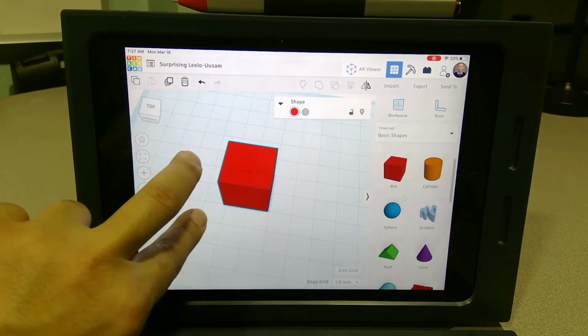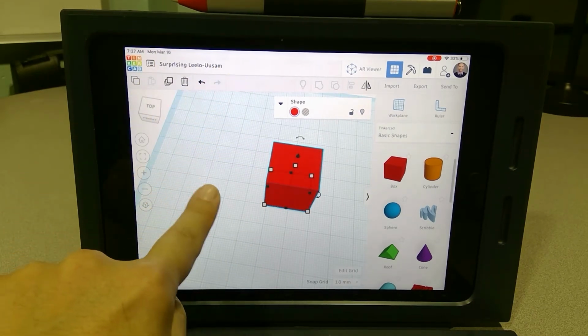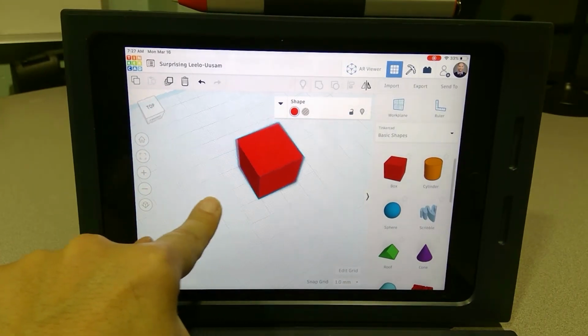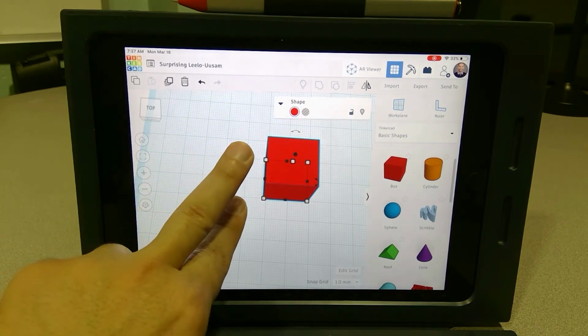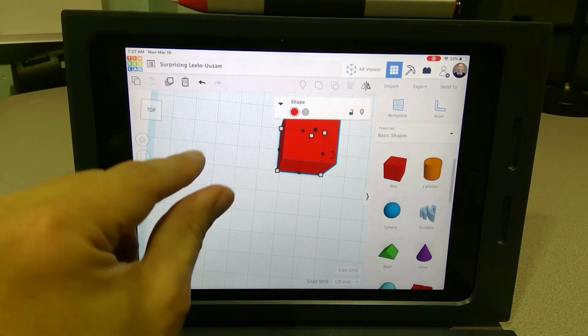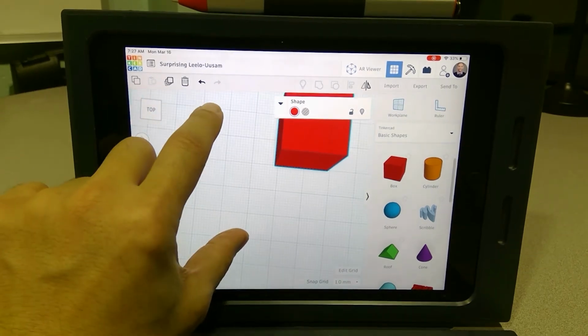So this is panning. So tilt is with one finger on the work plane, dragging. Pan is two fingers on the work plane, dragging. And zoom is two fingers moving closer or further apart.